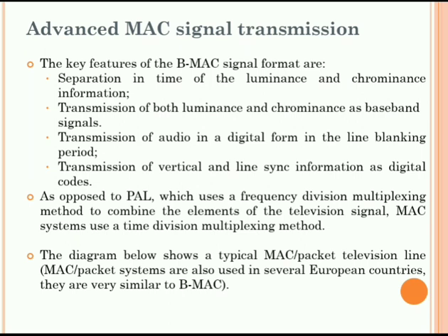Now, let us see the different technical challenges that we are facing for MAC signal transmission. Although the MAC technique is capable of superior video quality, similar to the improvement of component video over composite in a DVD player, its major drawback was that this quality was only ever realized when the video signal remains in component form from the source to the transmitter. If at any stage the video has to be handled in composite form, the necessary encoding and decoding processes would severely degrade the picture quality. That is one of the challenges in the MAC signal.